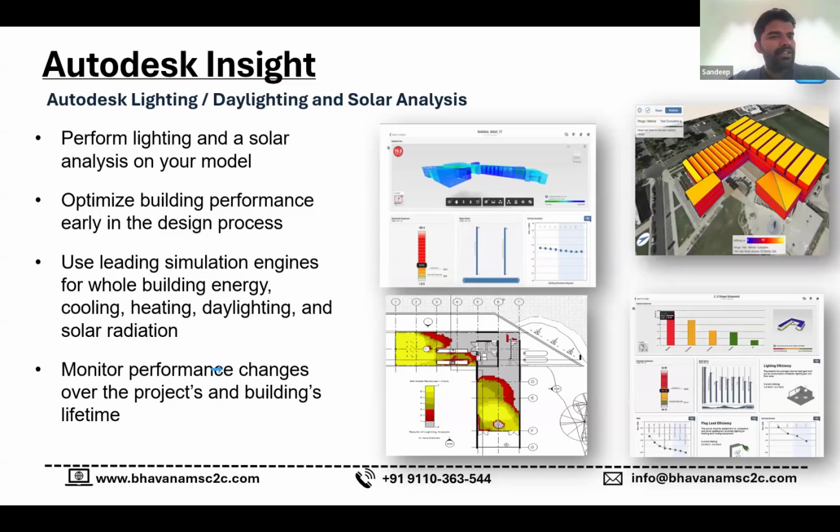So using this Insight option, we can have this study here. What is the orientation of the building that I can adjust so that the lighting will be for 6 to 7 hours, right? Similarly, you can perform the solar analysis, wind analysis, heating analysis, cooling analysis, everything. So this entire data supports sustainability, right? This will be helpful throughout the project life cycle, throughout the building life cycle. Getting it? So this we can do from Revit, right?